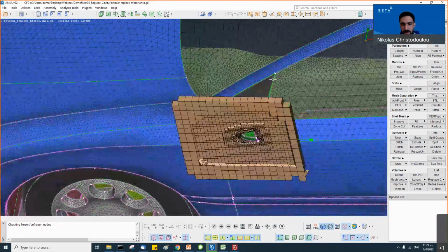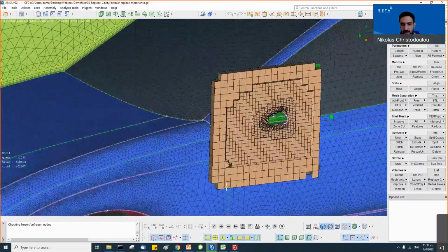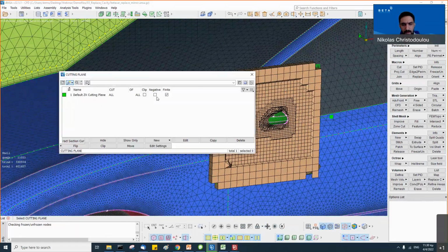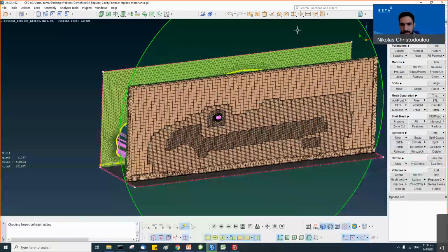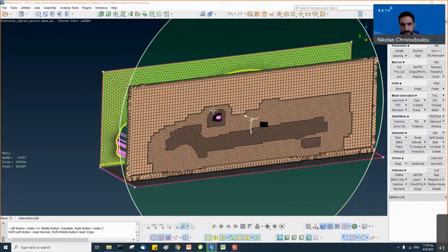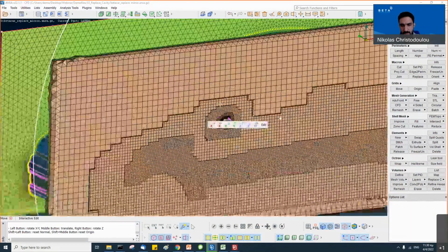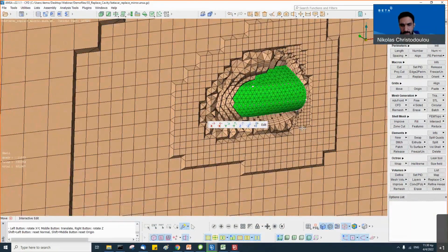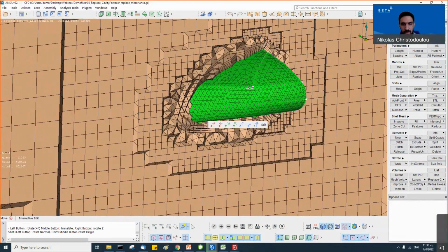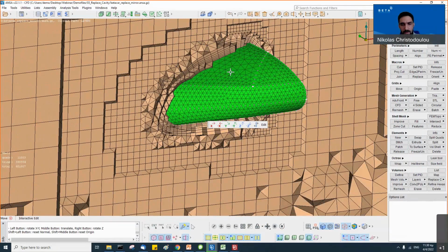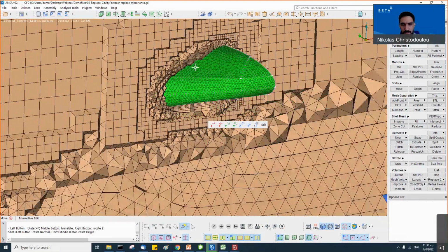And you can see there's no buffer zone around it. And let's actually inspect that by deactivating the finite plane. And let's have a look if we move it, how the volume mesh is properly built around the new mirror and the layers.